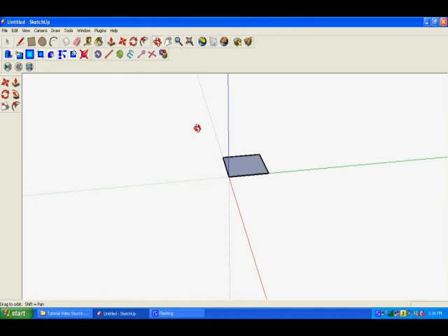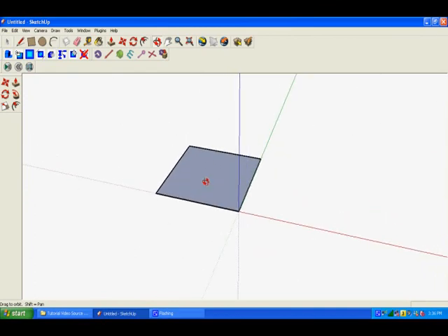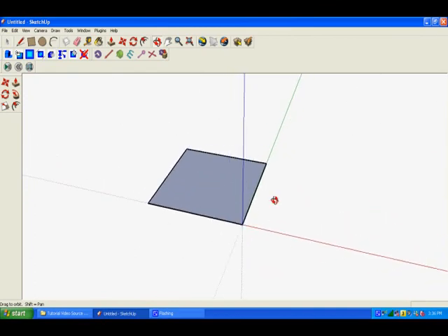So I'm going to design sort of the bottom portion of a pyramid, and in so doing, the first tool that's going to help me here is this offset tool. If you look at the top here, it says offset. I'm going to click on an edge, and what the offset tool lets you do is build a dimension with the same relative dimensions of the edge that you clicked on, but with different absolute dimensions, as you can see. So I'm going to click that, get rid of this face. It'll become apparent what I'm doing here pretty quickly.